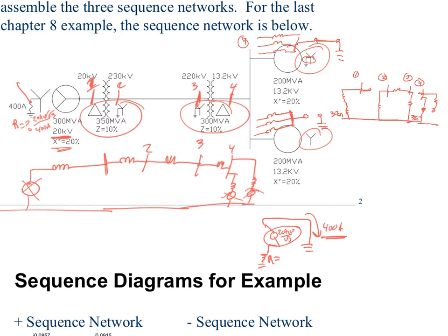So when you do your Y bus for that bus 4, would you still add that impedance in for the other? Good question. So this one right here, do I add that impedance there into the Y bus? If I'm building my Y bus 0, and I'm way down here at the 4, I'm going to have the 1 over 3ZN plus Z0. Do I add that impedance there?